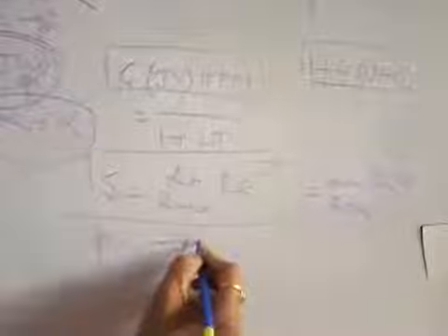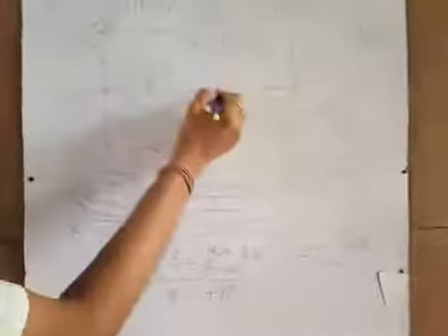So actually, when you express this semicircular path by the expression s is equal to limit r tends to infinity r e to the power j phi, basically this phi varies from plus 90 degrees, moving in the clockwise direction, to 0 degrees at point C, to minus 90 degrees at point B. So this is the total expression for this semicircular path.